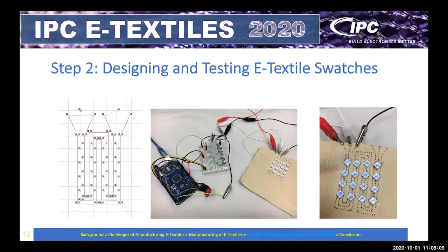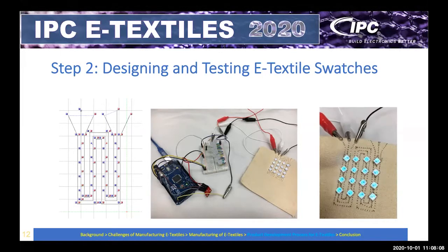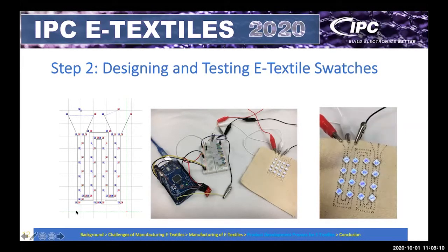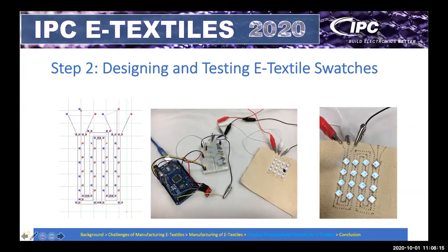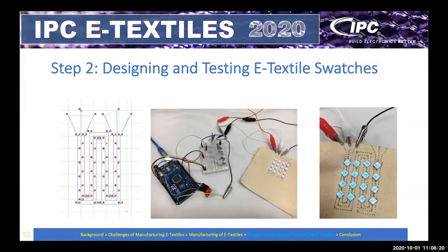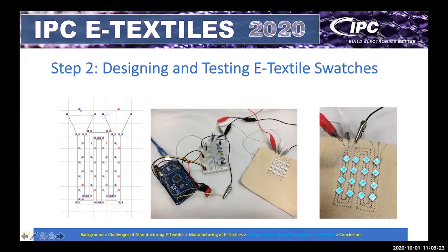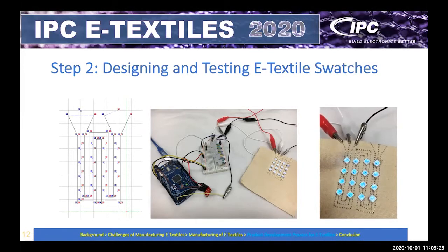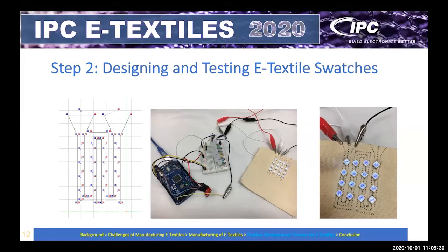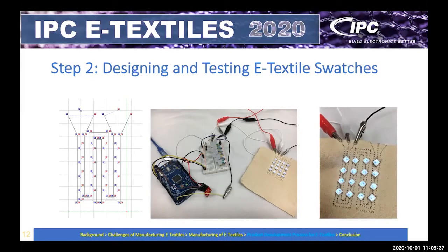So for example, here is a process where you design a circuit using a programmable sewing machine, and then you stitch using the sewing machine, and you use a surface mount component and solder them directly into the traces, and then you test the system to make sure it is working. And this is the stage where you also select all the materials you need. For example, this includes the material you need for making the garments, such as fabric and so on. Also, you need to select the materials needed for electronic component integration, such as sensors, actuators, etc.